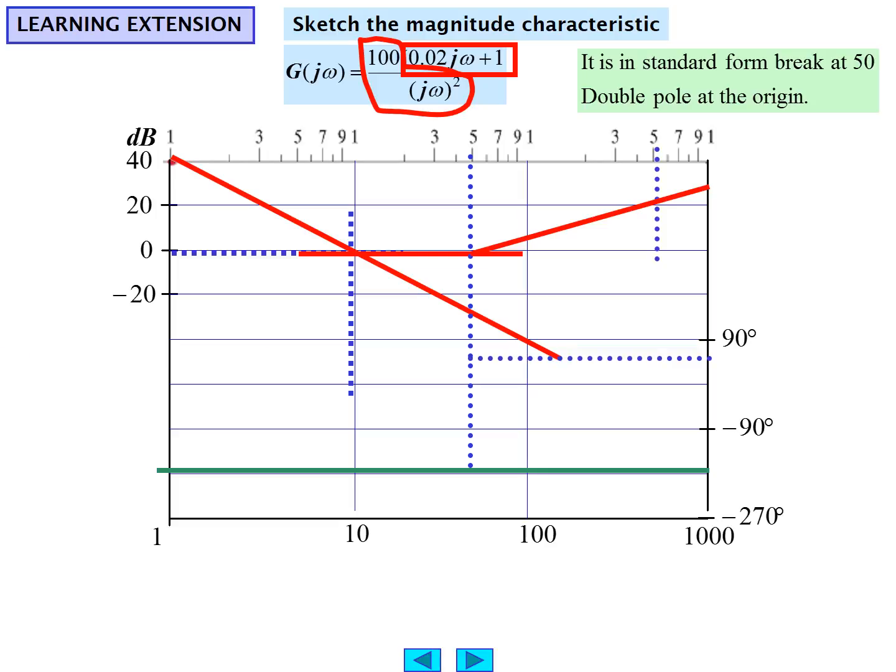And we have our other asymptotic behavior as a result for phase angle. And we have our same conceptual idea about what happens there. It's plus 45 degrees at the break frequency, going up at 45 degrees per decade, filling out the phase angle. So the complication was the double pole at the origin, which we handled by grouping it together with the gain term.